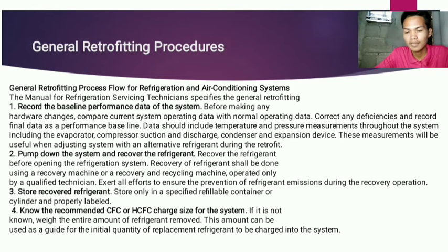Recovery means transferring the system refrigerant into a refillable refrigerant cylinder. If the refrigerant was not contaminated by a compressor motor burnout or other cause, it may be of adequate quality to be charged back into the system after the repairs are completed.